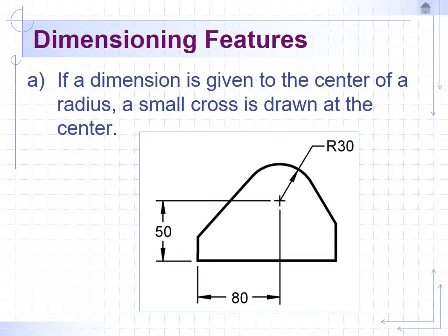You can insert a center mark in AutoCAD using our standard center mark tool, and then explode it, remove all of the extensions on it, and just be left with this nice little center mark that makes a good basis for annotation. So you might consider that if you think that works for your drawing.